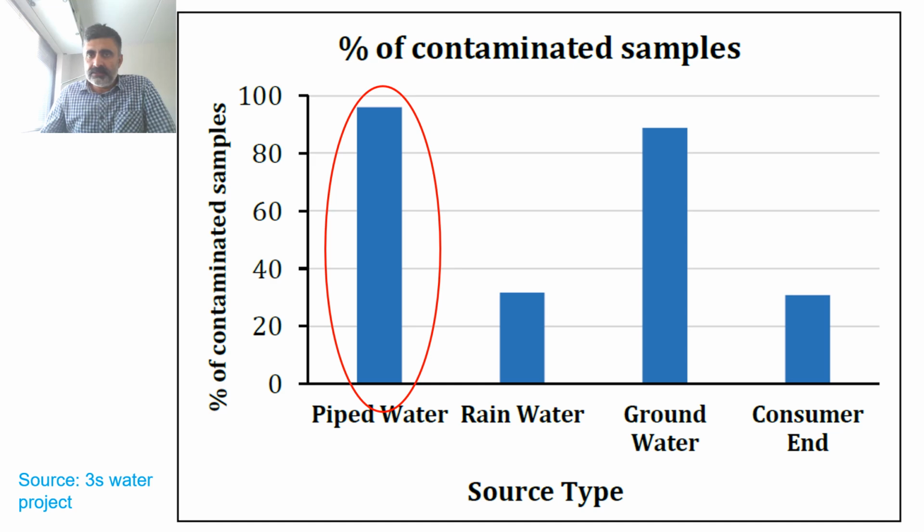When we looked into the details of this, we realized that sometimes the required chemicals like chlorine supplies do not reach water treatment plants in time. So the operators are forced to run the system under suboptimal conditions. On top of that, certain construction and maintenance issues have caused the groundwater and other contaminated water sources to leach into the water supply system even after chlorination.